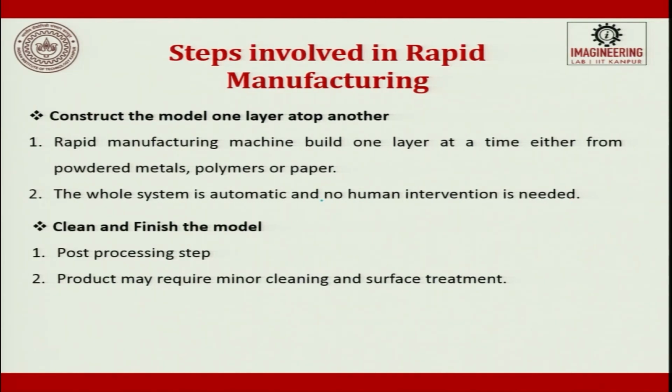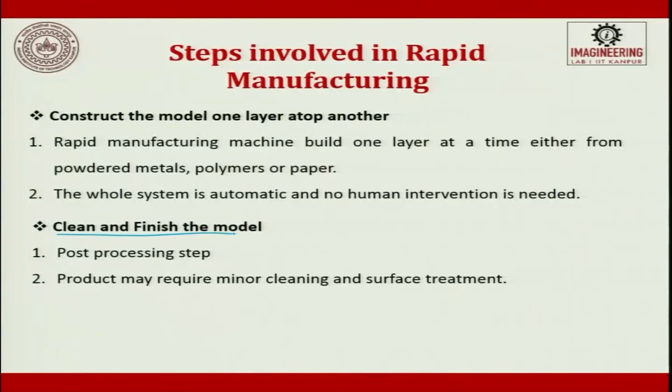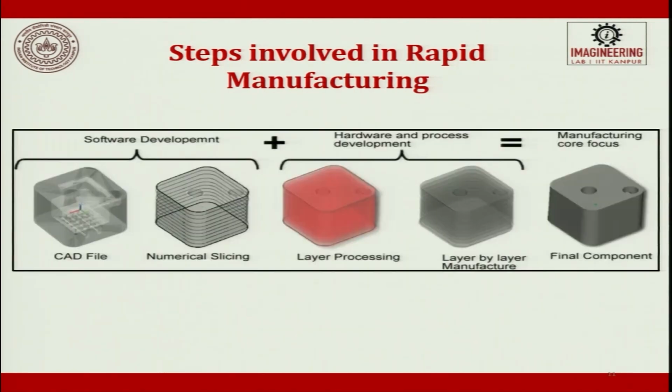Then once the object is made, you will have small errors which are getting developed, or it might need post processing operations in terms of giving color, strengthening, whatever it is. So, the last step is post cleaning, which is nothing but cleaning and finishing the model. Post processing steps are involved. The product may require minor cleaning and surface treatment to meet the requirements.